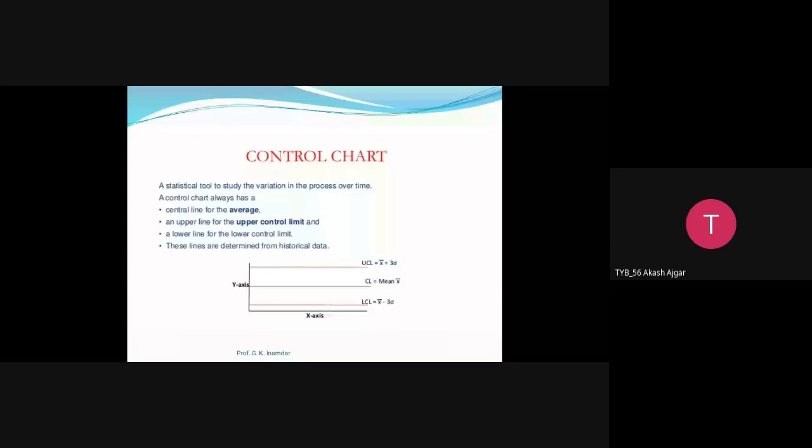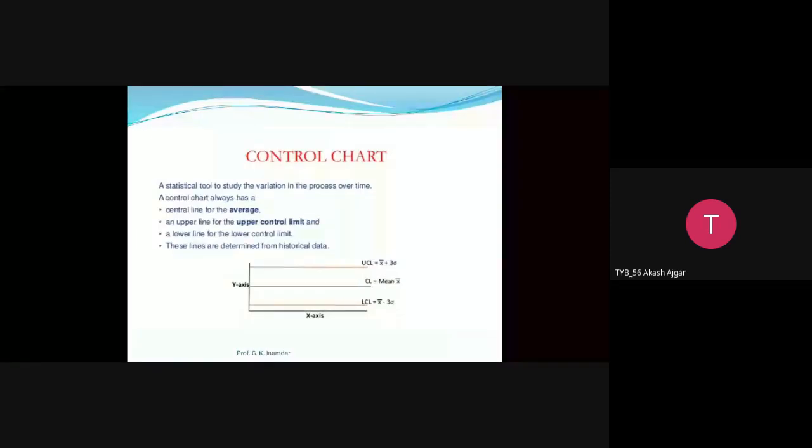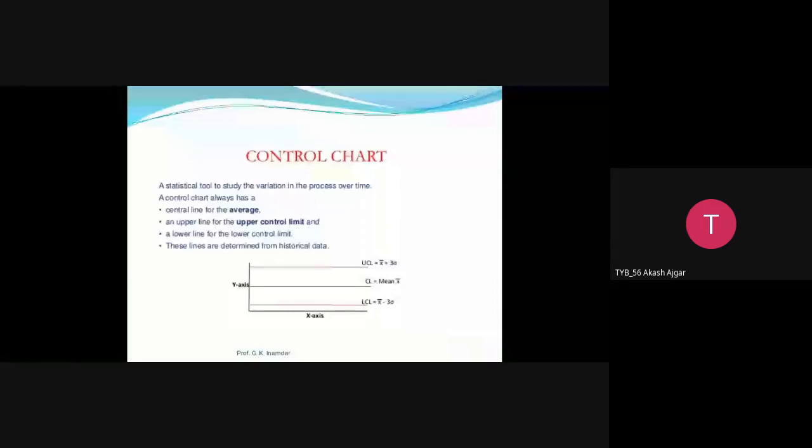A control chart is a graphical representation of the collected information. Whatever information we have collected from the processes, we represent using different control charts. It is just a way to represent the collected information. The information may pertain to measured quality characteristics and judgment quality characteristics of the sample. For example, from 100 parts we take randomly 10 or 15 readings as a sample, and we check or measure their performance.